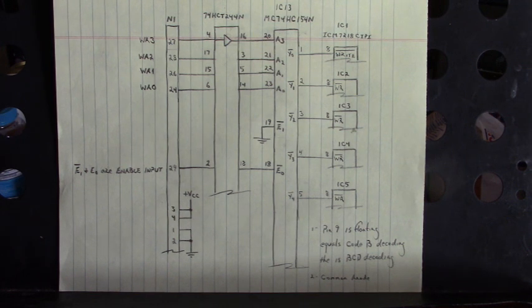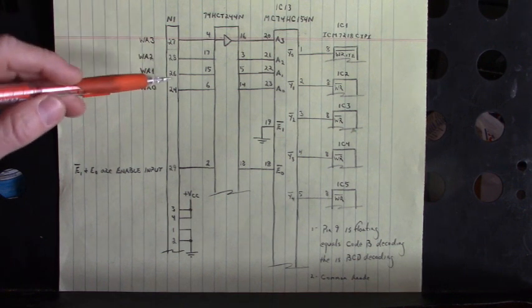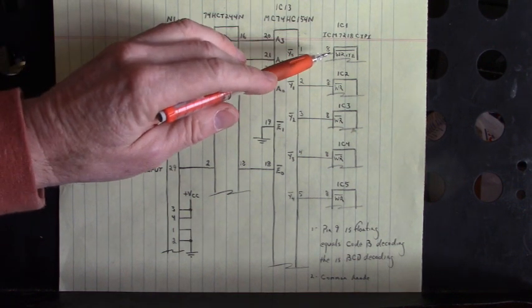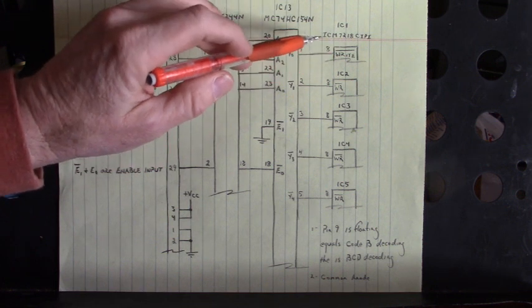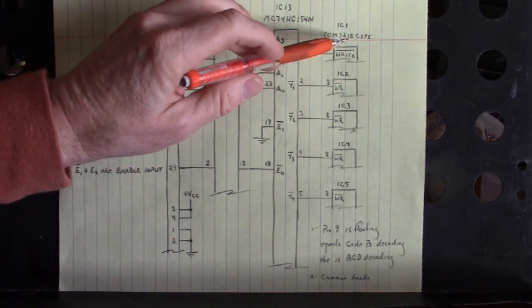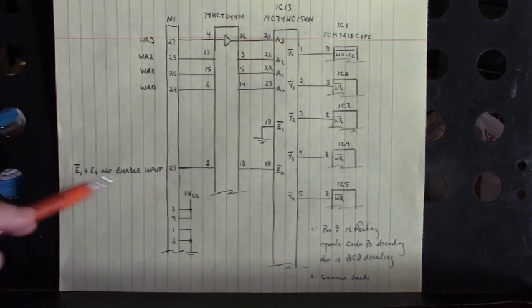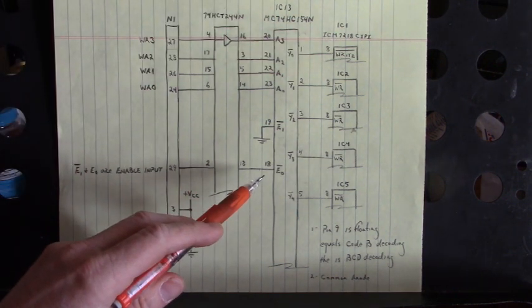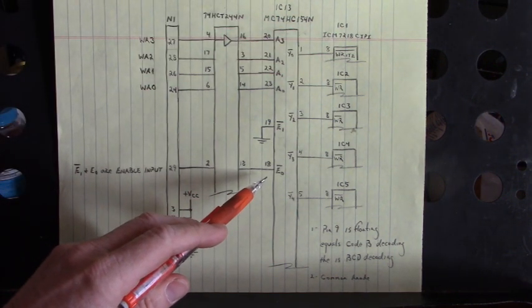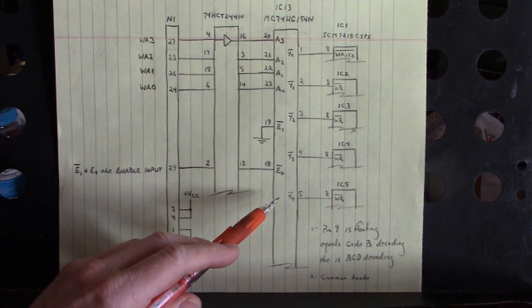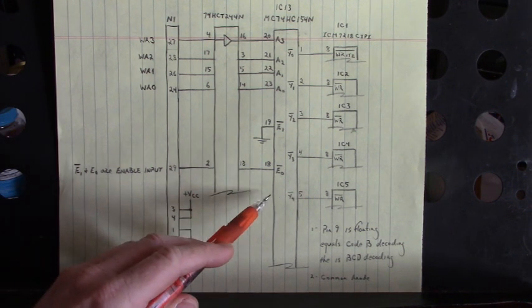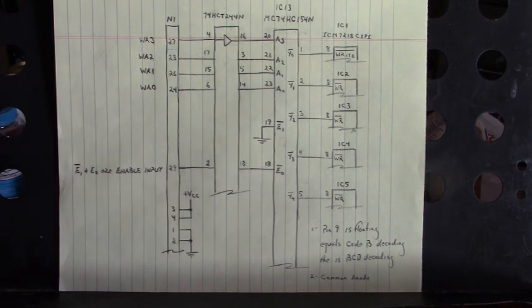There's a lot going on there. It's confusing. I even confused myself for a little bit. So we set the write address to select which ICM7218C that we're writing to, and then we drive this input enable low, from high to low to high.